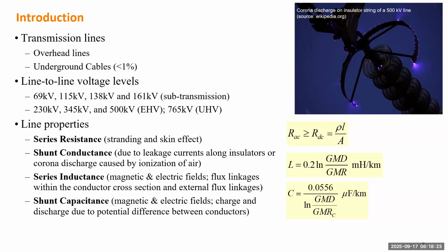And so in an AC circuit, we only need to know the AC resistance is slightly higher than DC resistance. How much higher? Just about a couple of percent, like less than 2%, if you operate the conductor in the 60 Hertz system. And inductance is basically just calculated by this formula.